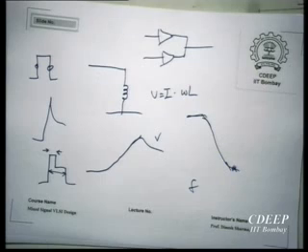And 8051 uses this idea. What happens is that there are ports and they have two drivers, and one of them has an XOR. So if the output is resting at a value different from what you are driving it to, then it turns on the high current driver. Otherwise only the low current driver is turned on. So that is a much slower thing, but it does provide that. So this is something somewhat smart.